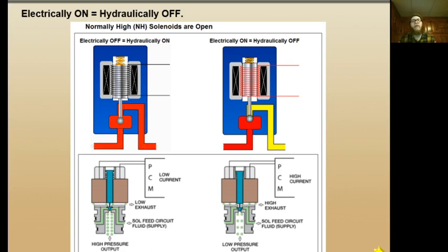The best information I've ever been able to get, and kind of the way that I look at it, is that there is a chance that a transmission may be left without power, right? So like a fuse pops that powers up all of our solenoids, a wiring harness melts, maybe our charging system starts to go bad, and voltage starts to drop below specified limits. The control module fails, right? All of these are options.